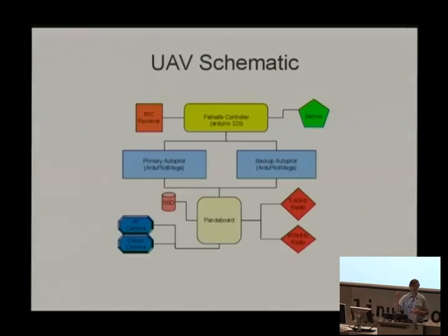The most annoying quirk, which I'm sure many of you have hit, is that when they initially boot, they start for the first couple of seconds in bootloader mode. So if you happen to squirt any data down the serial port for the first couple of seconds, it overwrites the firmware, which is really inconvenient because you've then bricked your device. You need to de-brick it.